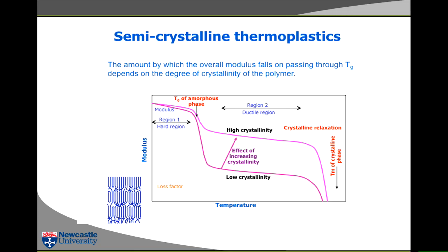Compared with the Young's modulus of steel. You know the Young's modulus of steel? If you don't, you should do, and you will do. Somebody tell me the Young's modulus of steel. Like X65 steel. It's around 10,000 megapascal. I'm asking about modulus, not strength. 2.1 into 10 power 5 megapascal. 210 gigapascals. Megapascal. You're right.